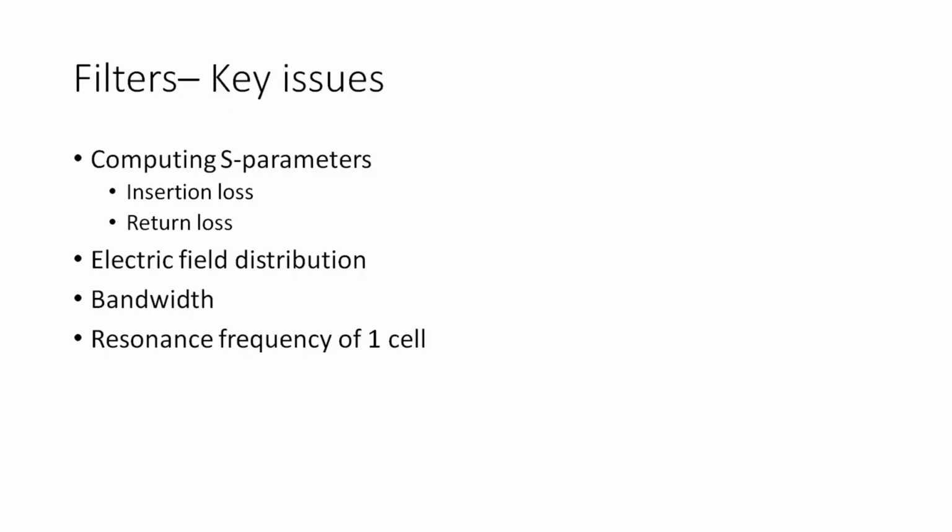Now let's get to the topic of the day, which is filters. As the name suggests, filters are passive RF and microwave components that filter some signal. If you have a signal that has a lot of frequencies in it, a filter's job is to pass certain frequencies that are of interest to you and block the rest of it. It's just as simple as that. But these passive components are very interesting because the way they are laid out and designed determines how good the filter is, what frequencies it is going to allow to pass through, and what frequencies it's going to block.